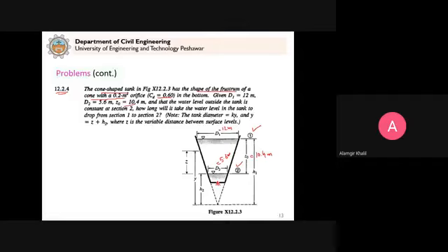What is given is that the tank diameter, that is, let's say whatever, small d or capital D, that diameter is equal to k times y, where k is a constant. It means that the diameter is changing with respect to y. It is not constant. This is given in the question. So accordingly you will work. And y is equal to z plus h2. This is now given in the question. So now we have to solve the problem. For these given conditions we have to put.